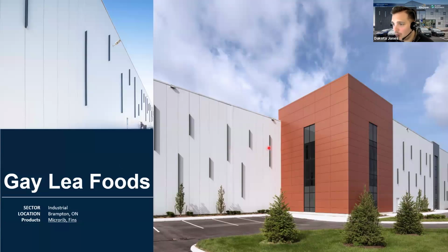And we have this kind of white, kind of monolithic wall, right? A little bit imposing, unfortunately. And so what we can do is take advantage of the steel on steel with the insulation on the inside. Remember, I mentioned you can riddle that exterior face with holes and never run into any issues. What we have is some surface mounted fins on here, running the length there so that we can give a little bit more movement to that facade. A really nice job of breaking that up while still being very economical.